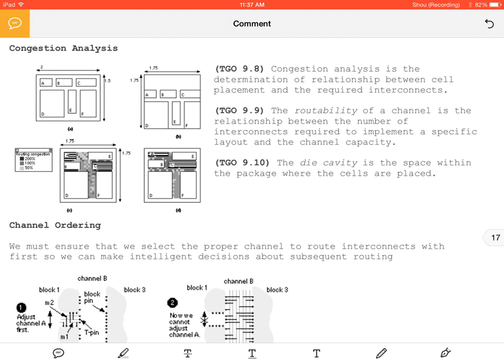So there's actually an algorithm called Espresso, which does approximately the same thing as Quine-McCluskey, but may have a little bit of area overhead, but it calculates significantly faster. A QM reduction is not NP-hard or NP-complete, but it's important to know that if you're trying to synthesize it quickly, or every single time you're trying to synthesize it before you check area, floor plan, then place and route, and area optimization, power optimization, interconnects optimization.